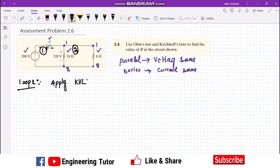And in this loop, when we apply KVL, we can see that if I say this one, Vs, equal to 200, this is, let's say, V24, and this is VR. So according to KVL, Vs, which is the voltage rise, is equal to VR plus V24. This is the equation here.